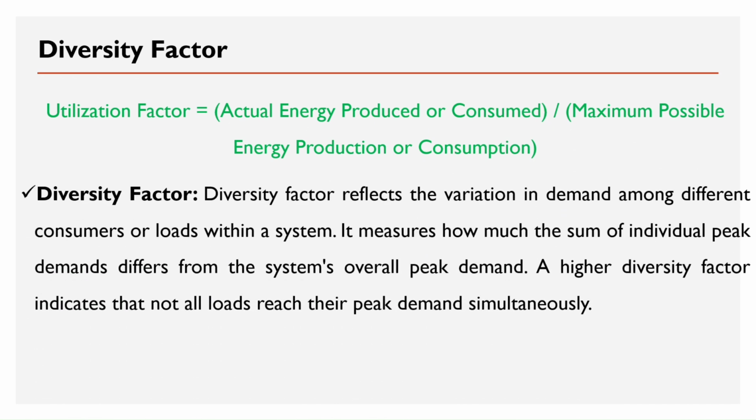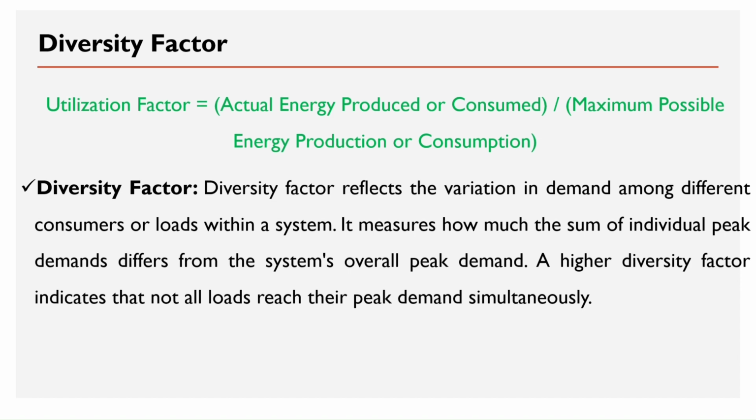Diversity factor. Diversity factor reflects the variation in demand among different consumers or loads within a system. It measures how much the sum of individual peak demands differs from the system's overall peak demand. A higher diversity factor indicates that not all loads reach their peak demand simultaneously.